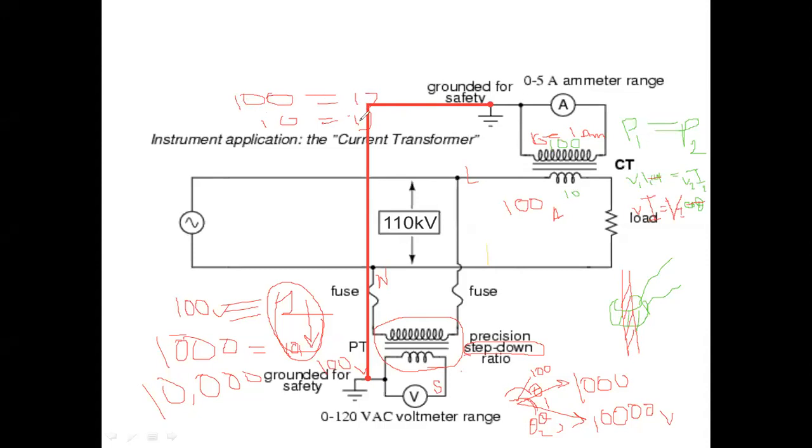If your meter is measuring 0.1 ampere, then actually your transmission line is carrying 10 ampere. In this manner, we can measure the current flowing through the transmission line, and then we just change the scale up to the requirement. This is called calibration. So in this way we can measure the high amount of current and voltage of a transmission line, distribution line, or any feeder line by your CT and PT.